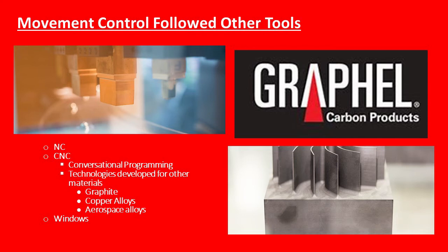So it's not just limited to copper to steel or graphite to steel. There are also specific technology tables for burning titaniums, for burning high nickel alloys, for burning carbides. So the technology of the spark settings themselves has greatly advanced. And then today, the most modern machines are using a Windows-based control or something like Windows. Extremely user-friendly, extremely capable, extremely powerful equipment.